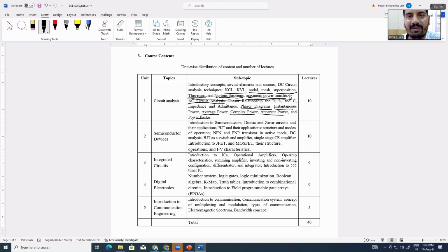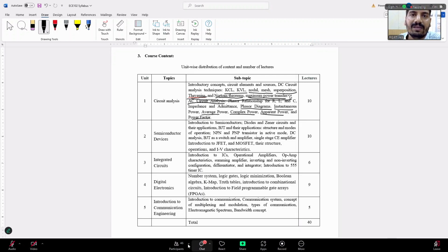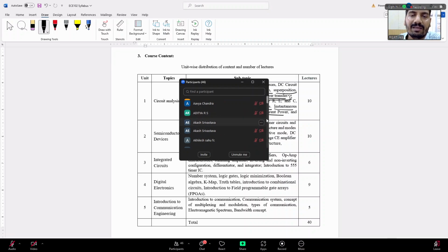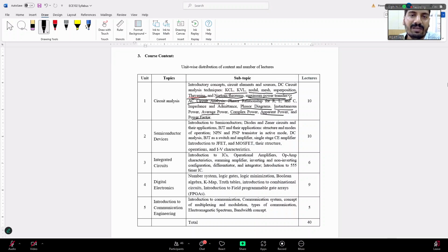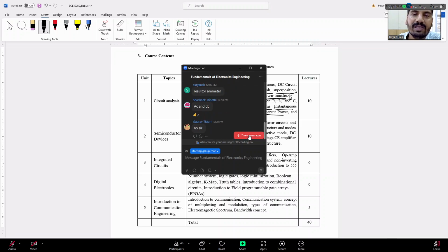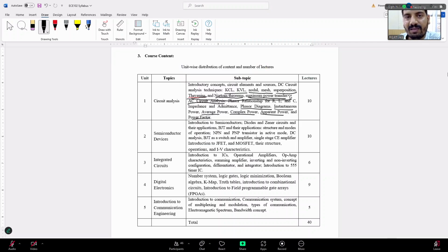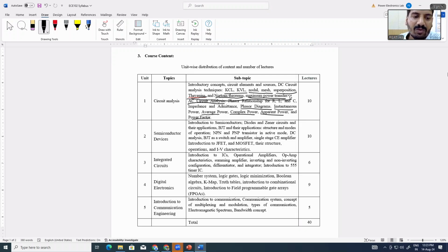So in that, if you calculate the angle theta, theta is equal to tan inverse X by R, right? That means the reactance component divided by the resistive component. So theta is equal to tan inverse X by R, right? It can also be defined as cos theta is equal to R by Z. So this power factor can be defined in many ways.